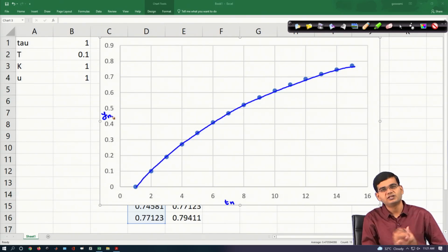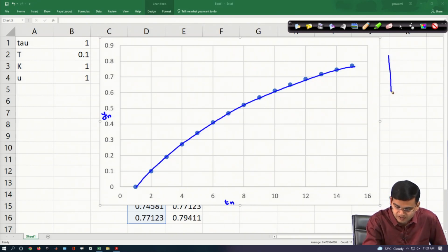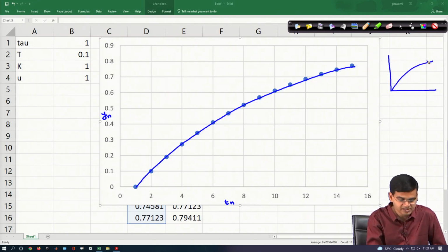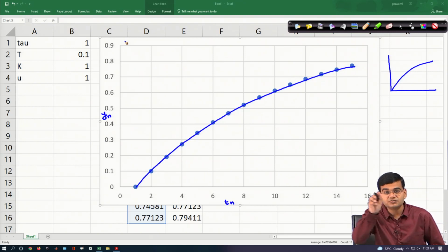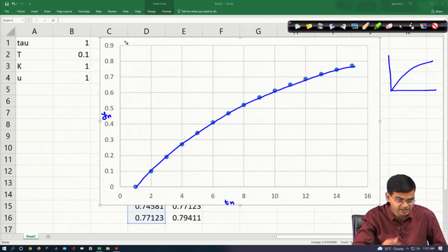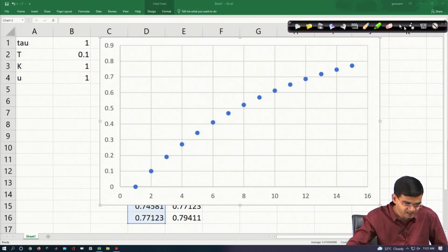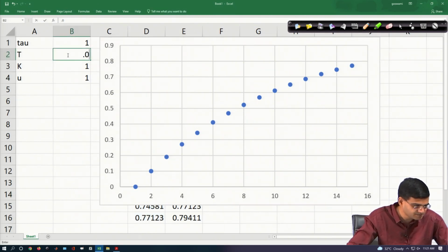Is this what we also got in the continuous domain? Yes, in fact we did, right. The plot looked like this, except that it used to come asymptotically to 1. Now, it also is reaching towards 1. Now, we can do one thing, we can change the parameters of the system, and let me make the time constant here little smaller, so that the dynamics becomes faster.